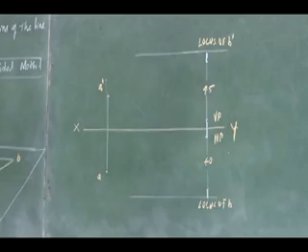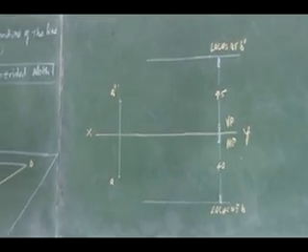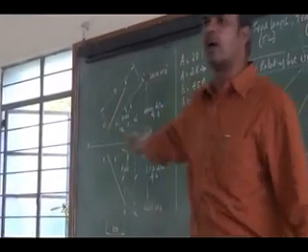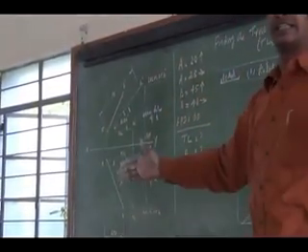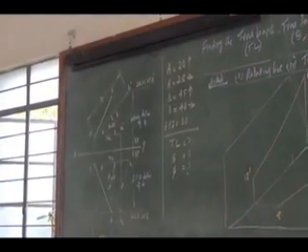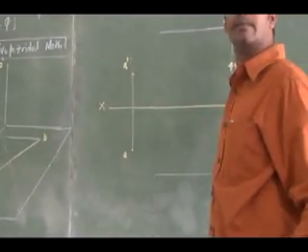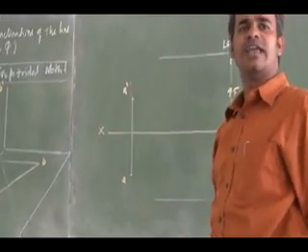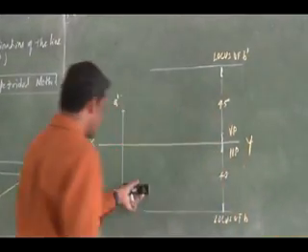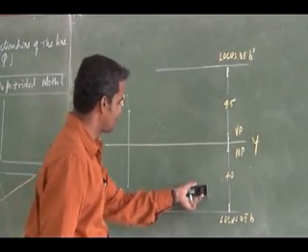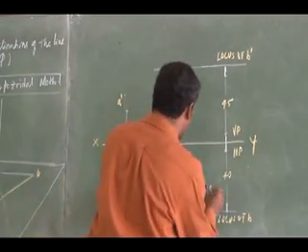So what is the other data I can use? The previous last class third problem, you use it as a template, right? What is another data I have? The end projector distance. I can draw two projectors. Okay, so one projector I have is A dash A. Another end projector is what? It is 60 mm apart from the end A. So another projector I can measure 60 mm. I can draw another projector.